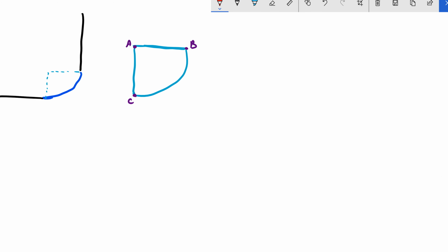This is horizontal, so we are going to have uniform pressure above this point, at the center, and we are going to call it F1, and you know how to calculate it. We have a vertical surface, exactly similar to the previous point I made. It is going to be applied a bit lower than the centroid, and we are going to call it F2. Let me draw the pressure here. It is going to be like this. Pressure here is going to be like this, uniform. And you know how to take care of both.